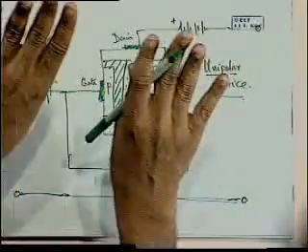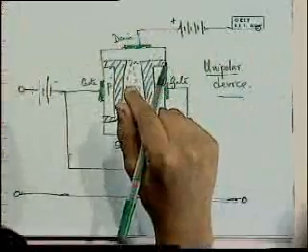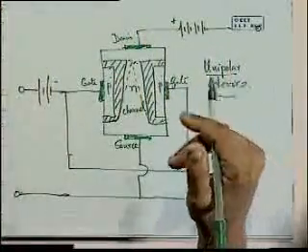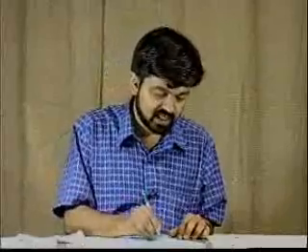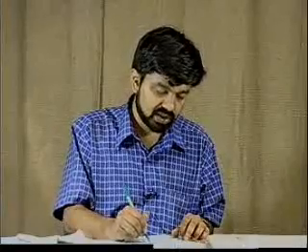It's sort of like a gate that is closing. That's the name, a gate that regulates the flow. Like dams where water is flowing from one side to the other, you can open and close these gates, and how much you open and close them determines how much water goes through. Similar idea here. As the biasing on the gate is increased, as it becomes more and more reverse biased, eventually a voltage is reached when you have completely cut off the channel.